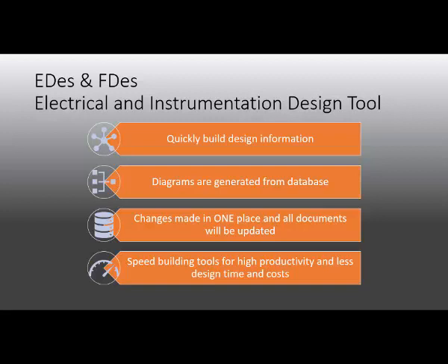Our EDes FDes is our electrical instrumentation design tool, and this is really created to assist the engineer to build their design information. So we're saying that the same effort that the engineer puts into putting all the information into Excel, by putting that into our database, it has additional benefit for them. And that is that it will create your loop connection diagrams, your junction box termination connection diagrams. It will create your instrument list, your cable schedule, your motor list, various reports that you can get from that same source of information.